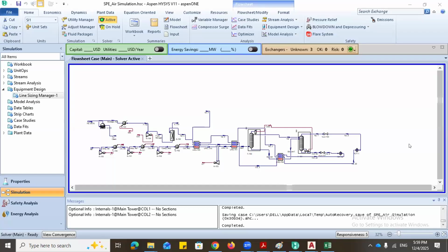But at the end, at the detail stage of design, we would have 100% completed our P and ID design. At the first stage of design, we should have gotten to 80 to 90% simulation, with the remaining 10% completed in the detailed design. P&ID will be completed also in the detailed design. We will also do our line sizing and equipment sizing in the detailed design, and all those things will start our 3D modeling. 3D modeling, not even in detailed design.